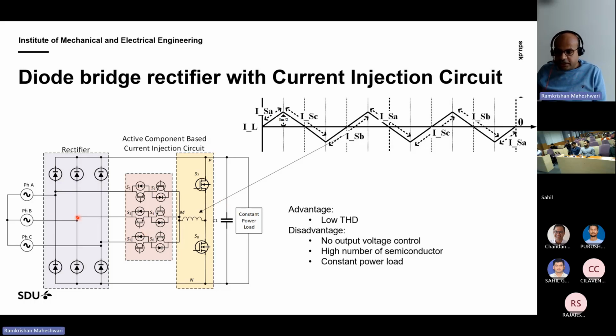There may be problems here because I showed in the simulation a direct connection to the phase, but it's not the case. You always have an inductor, and when you go from one phase to another phase with this phase selector switch, you need to take care of this inductor current change on the grid side.